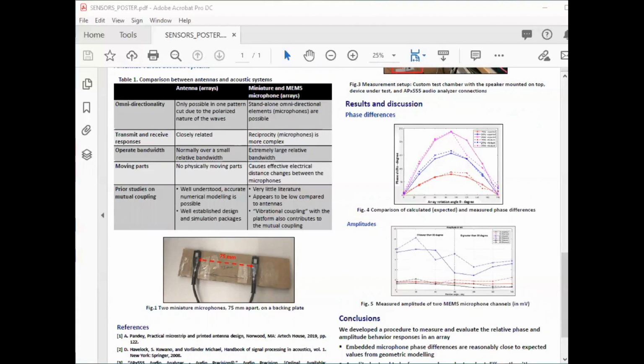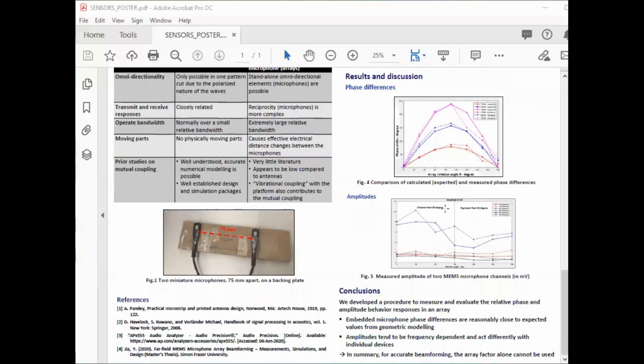Amplitudes are expected to be identical for omnidirectional microphones ideally. However, in Figure 5, the amplitude varies with different rotation angles theta, and is also more sensitive at a 2 kHz frequency. The measured amplitude cannot be considered ideal, and beamforming would be affected by their large variations across the sampled frequencies and angles. To conclude, our method presented estimates of embedded microphone directional response samples.